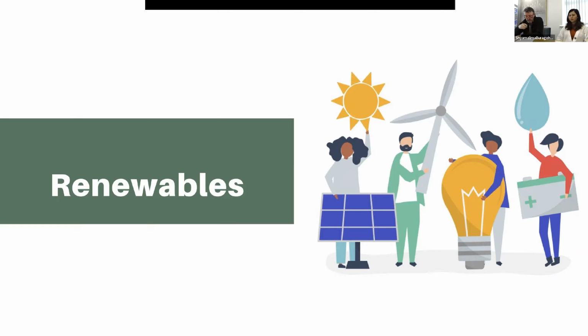If you're heating radiators from heat pumps, they tend to have to be low temperature radiators because it's not suitable for bringing water up to high temperatures, 60 and 65 degrees. It's more comfortable working at 30 to 35 degree range, and it's most efficient there. It can be used for cooling, as in your fridge or your freezer. The heat pumps are just a reverse of a fridge, generating heat instead of coldness.